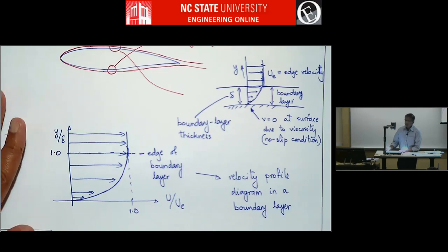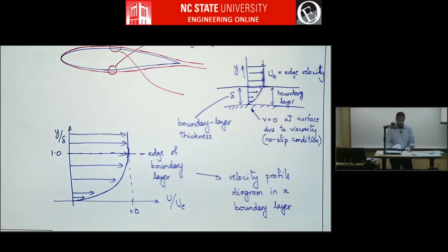We'll have many similar sounding terms, right? We are talking about velocity distribution. We have been talking about that earlier. That's like a CP distribution. That is how the velocity varies from leading edge to trailing edge on upper and lower surfaces. Something similar is velocity profile. It sounds similar, but it's very different. Velocity profile is how the velocity varies inside a boundary layer.